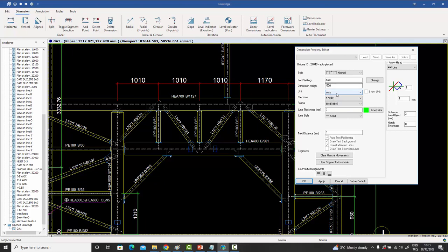And besides this unit option, there is another option for the precision. Previously we didn't have this variable directly in this form. Now we have these different precision levels, and the first ones are typically used in millimeters. So rounded off to the nearest 0.25, rounded off to the nearest tenth or 100th or 1000th. But now we have added these three extra ones, which is rounded off to the nearest 8th, nearest 16th, and the nearest 32nd, 1 over 32. So this is another precision variable which we've added to the dimension.